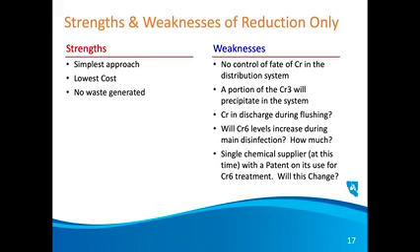It's in its infancy as a concept. There's no control over the fate of that chromium in the system. A significant amount of it may precipitate in the distribution system. So I have questions: during flushing, am I going to exceed a discharge limit on chromium if I'm flushing a pipe that's accumulated years of chrome 3 in it? Will the chrome 6 levels increase dramatically if you go through a main disinfection? Even though you flush it afterwards, that disinfection may redissolve a significant amount of chrome 3. I don't know.